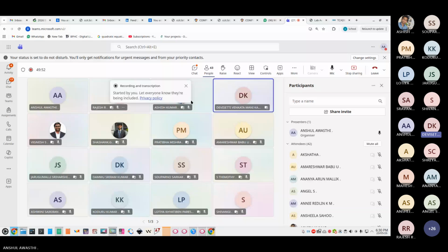We just selected the aluminum region because of P side and N side. In the script we have to define the region because we are writing, so it does not know where to place that contact. But in the GUI, we know where the contact is, so we directly place it there. In the script file, it will automatically take the center.